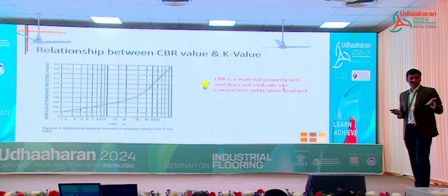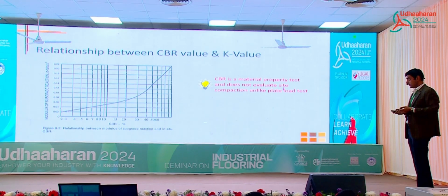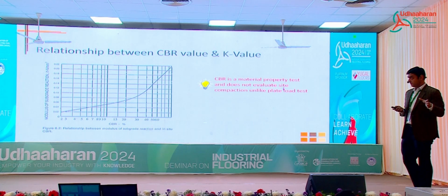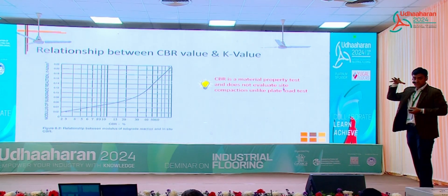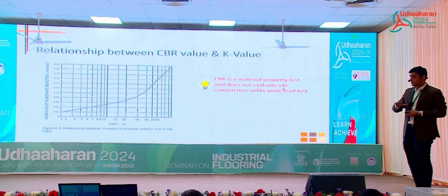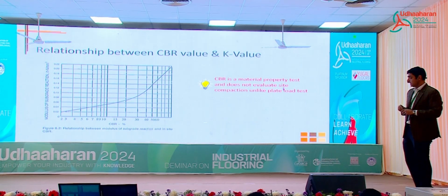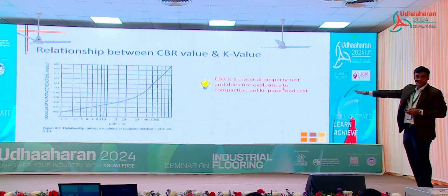Now CBR is also commonly used for road work. That is actually the standard for bituminous roads. But we try to avoid that when it comes to floors, because CBR is a material property test and it doesn't actually test the compaction that you're doing at site. So you're better off doing a plate load test and a combination of Proctor density. I'll go over that also in a different slide. But if you are doing CBR, this is a good reference.